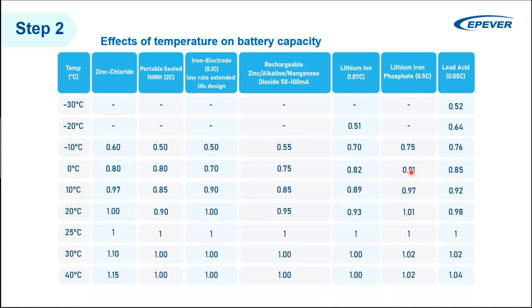Prolonged exposure to cold temperatures also has a big impact on the battery performance and the battery safety. When the temperature drops, the internal resistance of the battery increases. So batteries have internal resistances, and when it's cold, this resistance increases. This means that it requires more effort by the battery to charge, so they will not be charged with their full capacity.